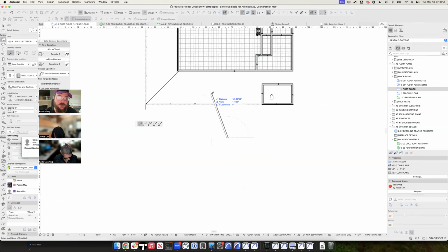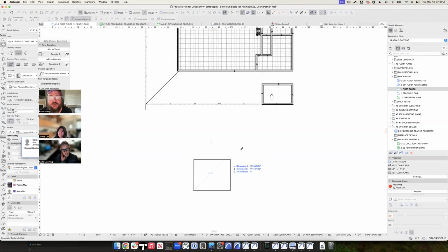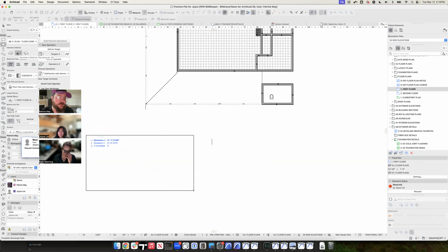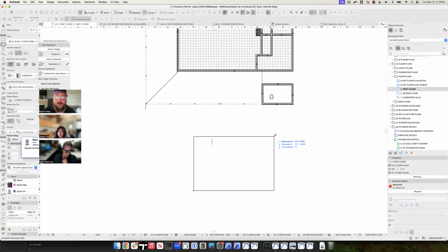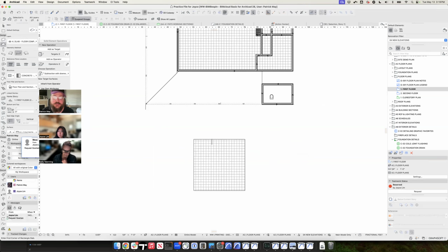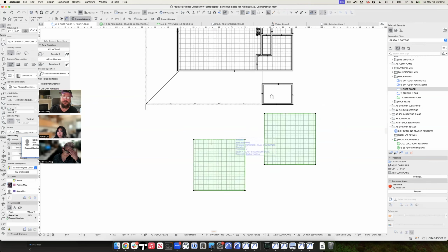One place that I really use the XY is if I'm drawing something that's rectangular, let's say a slab or a morph or a mesh or something. You can use the geometry method of a rectangle, and I can type X20, Y20 and get a rectangle, rather than using the polygon method and typing Shift R20, Shift R20, and then dragging it around, right? So it's a fraction of the time to type X20, Y20.